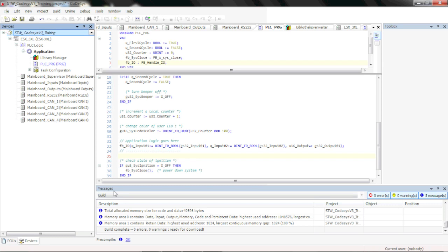One more issue is that if you don't have CAN termination on your bus properly, say 120 ohms or 60 ohms for bench testing would be fine, across CAN high and CAN low. If that's not in place, you're not going to get proper CAN communication and the gateway won't be able to connect to the controller. So make sure your CAN termination is there before trying any communications. So these are just some of the common problems you can run into. There are more, but these are the common ones that we see a lot.